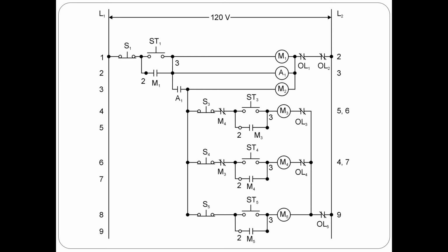First, let's take a look at what this circuit holds. We're going to identify all the different holding contacts that we have inside the circuit. This circuit has 4 different holding contacts, and they're all in parallel with certain start buttons. If I were to have something that was not holding but would start, I might think maybe there's a problem with the holding contact. I should also be able to identify any interlocking.